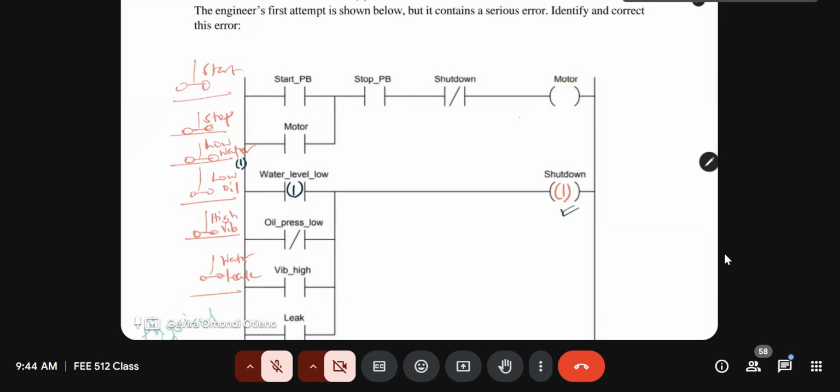In other words, if this one was connected as a normally closed contact, just saying, then the low water level physical device is already passing logic, it's already a logic high. So the virtual device, if it's a NOT function, will give me a logic 0, because if it receives that logic 1, it will give me a logic 0. And logic 0 does not match a condition for a shutdown. So that is a confirmation that this one should be connected as is, in the normally open position. Good. Let's move on to the next one.